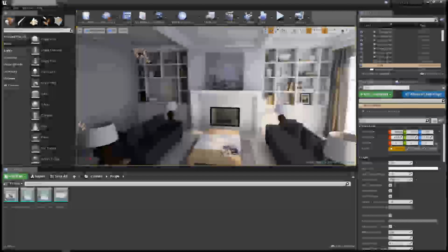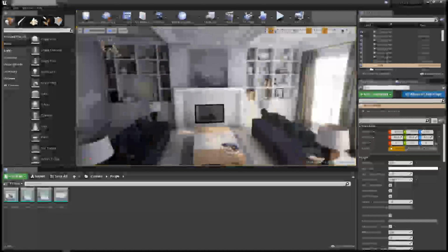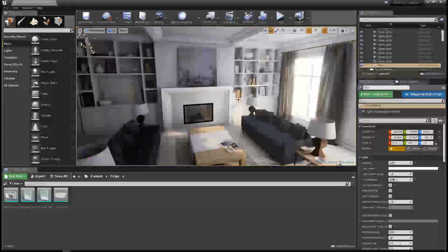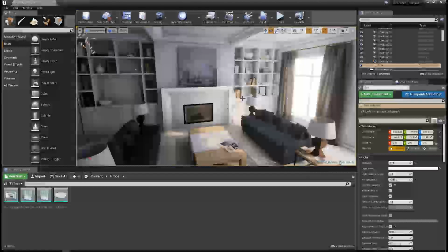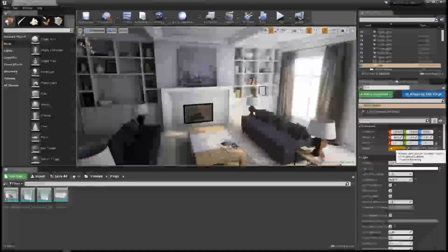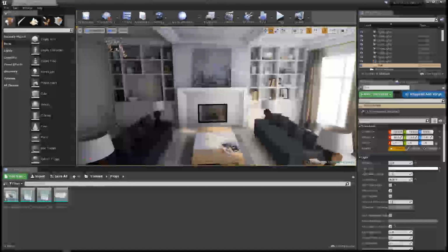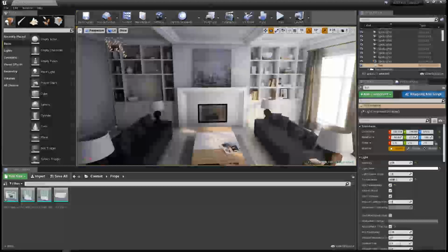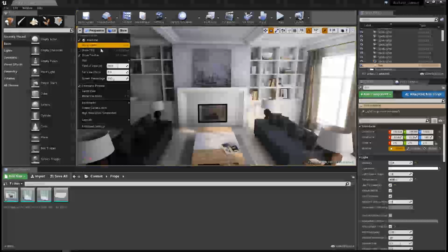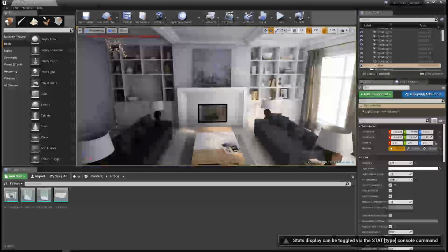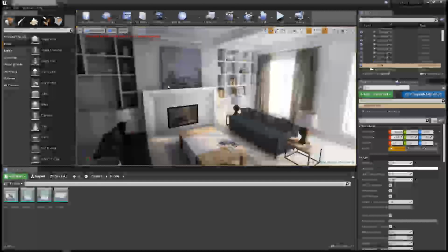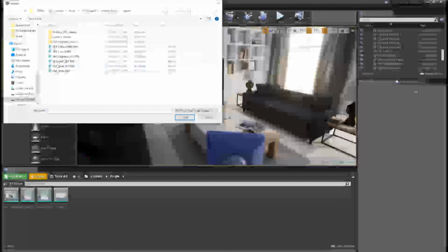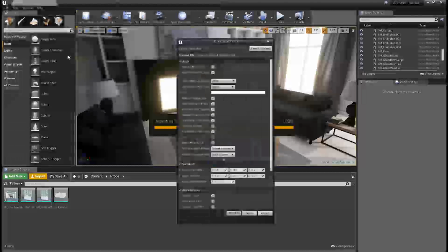Now, obviously right now it says preview on my meshes here in Unreal. That means I need to bake my lighting because currently my sunlight is, we set it to movable or dynamic, and that cleared out the baked lighting, and then we set it to static. So now we need to rebake the lighting. Also up here, it would tell you normally that lighting needs to be baked, but I have my stats turned off. Turning that on, we can see we've got a red message here reminding us that we do need to bake our lighting.